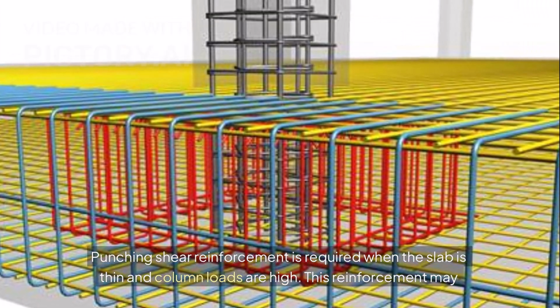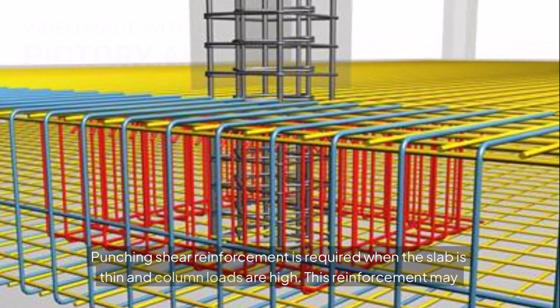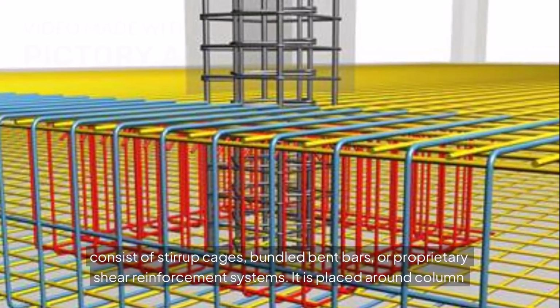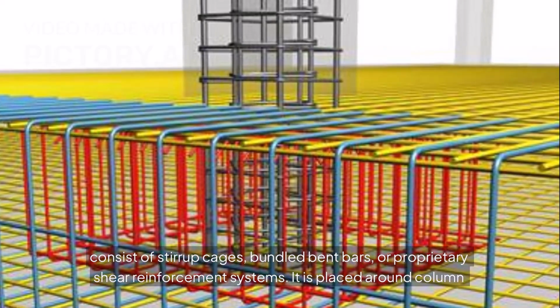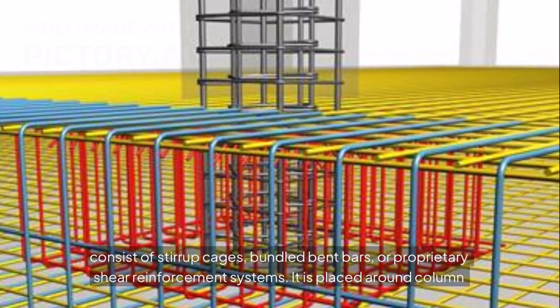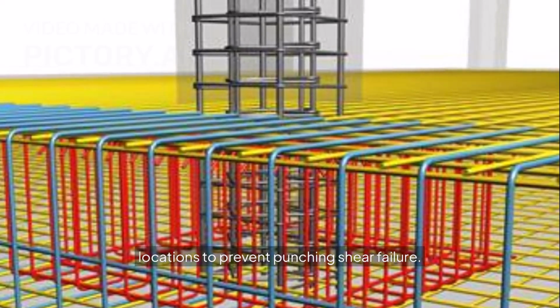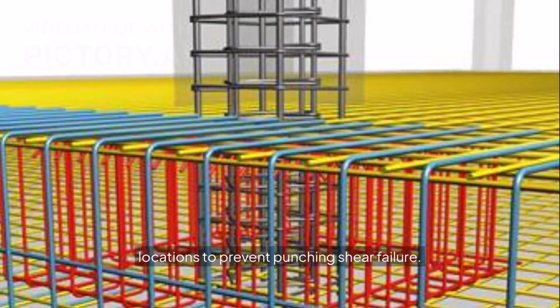Punching shear reinforcement is required when the slab is thin and column loads are high. This reinforcement may consist of stirrup cages, bundled bent bars, or proprietary shear reinforcement systems. It is placed around column locations to prevent punching shear failure.